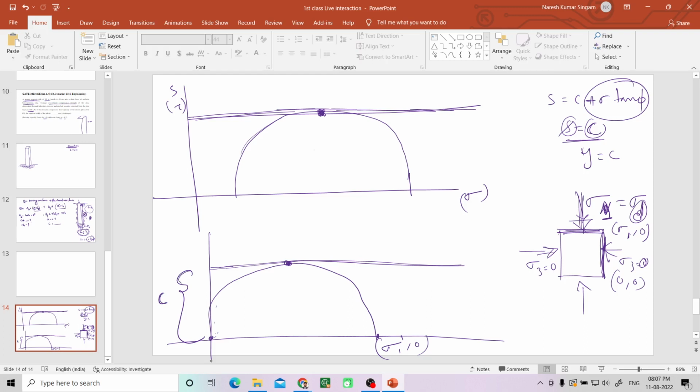So here, if you remember, the unconfined compressive strength, which is QU, is nothing but the simple vertical compressive strength, and that is given as 100. If you remember, that means sigma 1 is 100 here, 100 comma 0. If you know the diameter is 100,